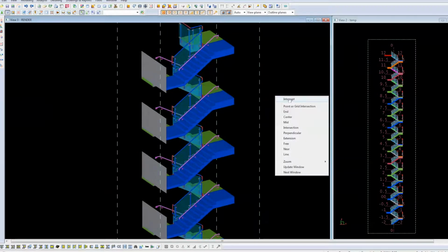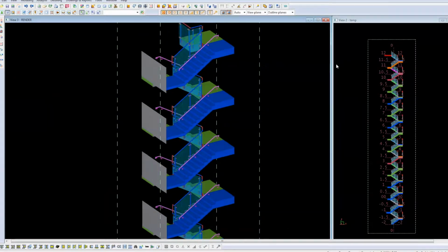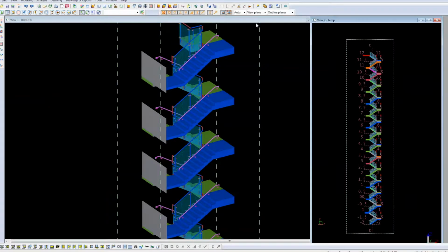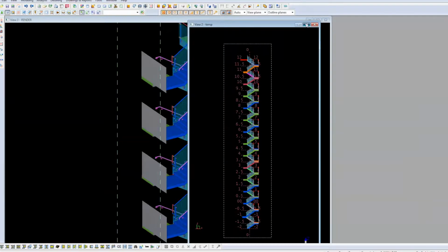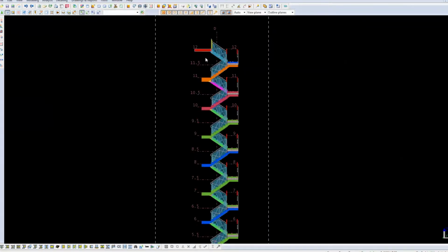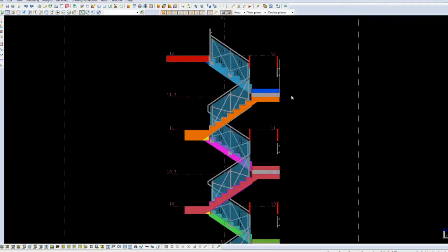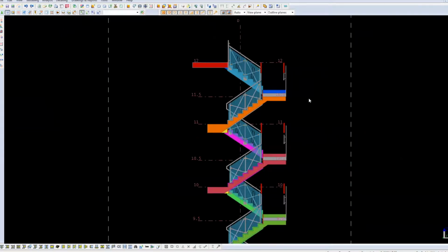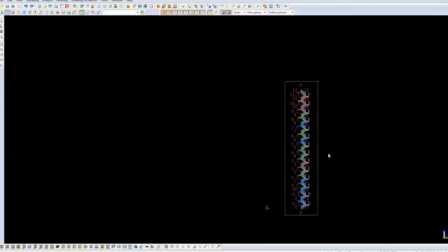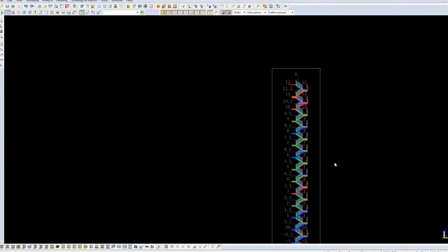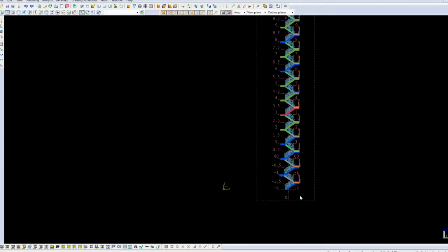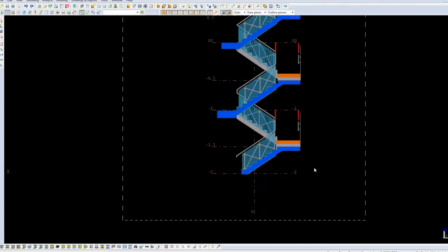And the reason I don't like people measuring in plan or sketching in plan is because you shouldn't be drawing in plan. You should be drawing or modelling in elevation. So this is how I like my information set out, in elevation. So before I went to site to measure this job, bearing in mind I knew exactly how I was going to measure it,